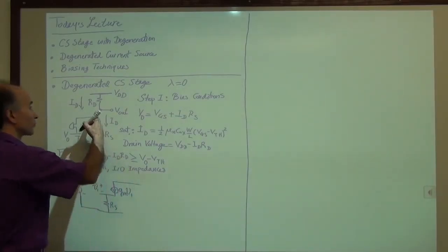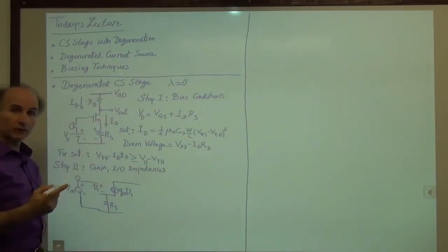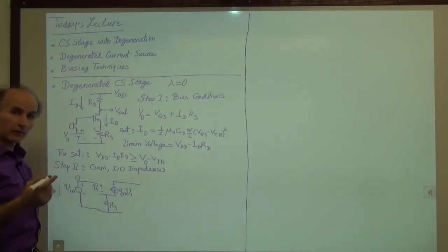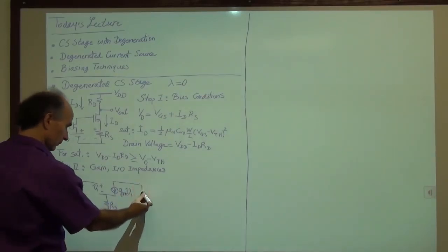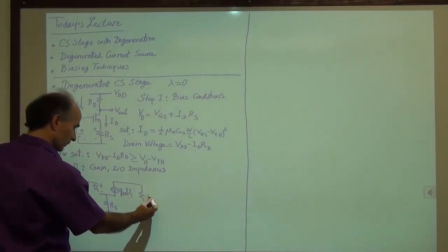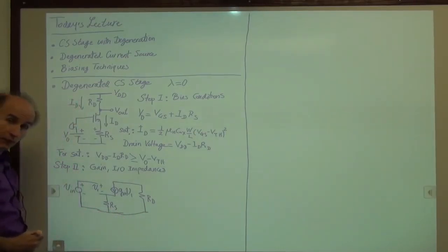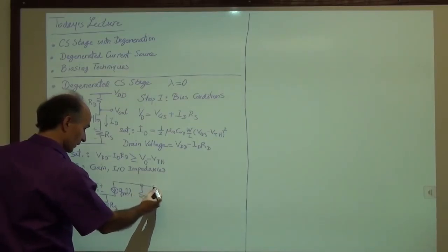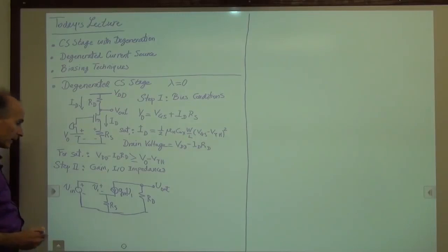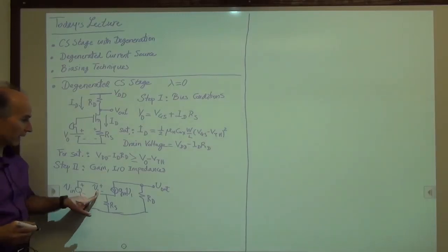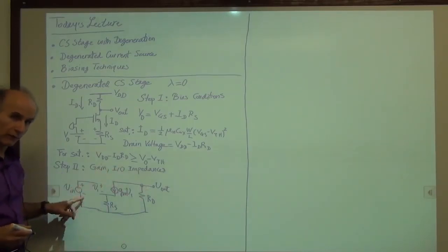And then from the drain, we have a resistor also to ground, because the supply voltage has 0 change with time. So it has to be a 0 volt supply, which means it's a short circuit to ground. So we have a resistor that also goes to AC ground, and that's what we have. We are interested in this output voltage with respect to ground, and what we would like to do is eliminate V1 so that we can find V out over V in.